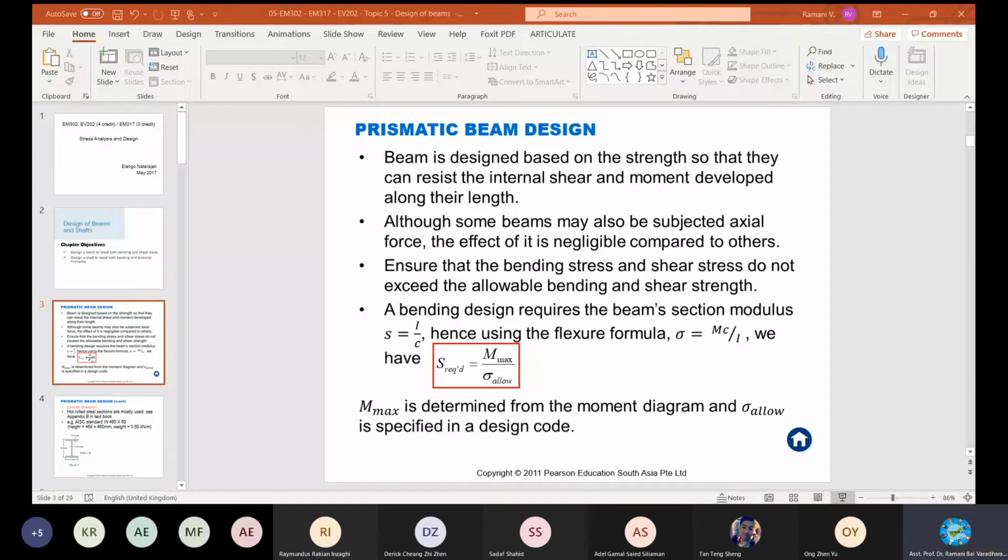And one of the codes will have this prismatic beam section. We'll have all the section names, area, depth, web thickness. This is all manufactured. This is already manufactured, and if you're going to use it at your site, it will be supplied to the site, to the contractor. You will have different sections, and then you can choose based on your design values for adapting in your construction.